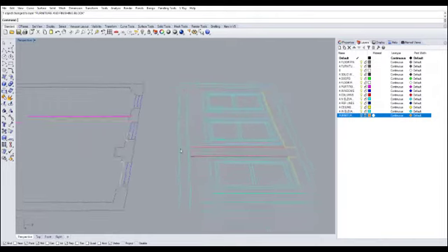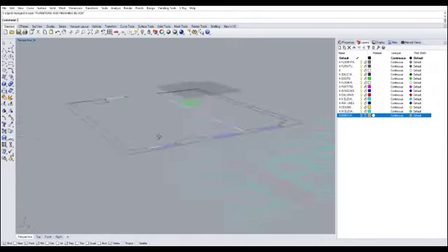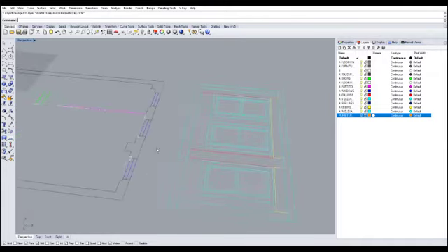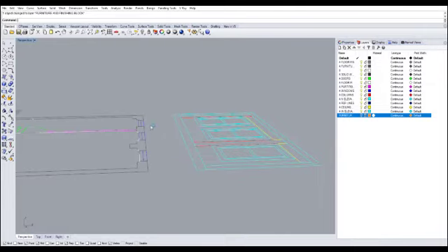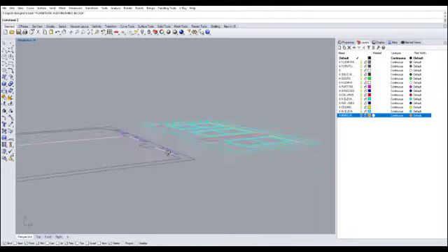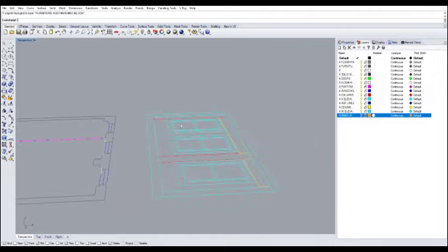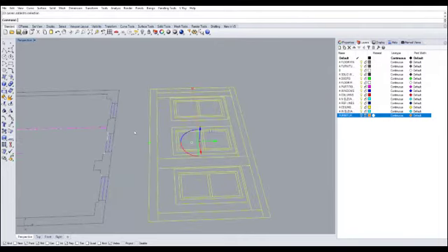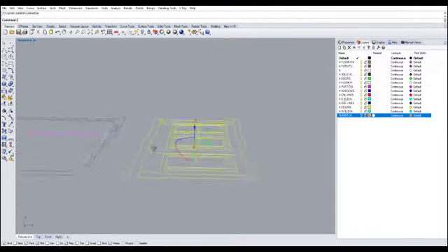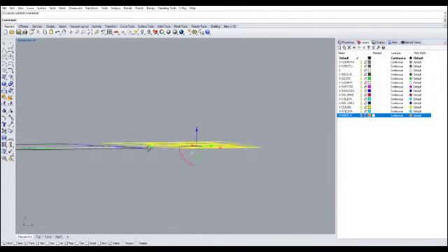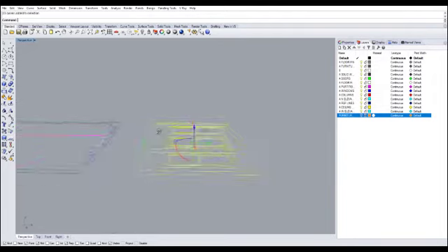And height information is necessary for us in terms of making a 2D plan into 3D, because it will tell us how to extrude or make it into 3D solids, or how tall or how high to make the 3D model. So for us to do that, let's also make sure that our elevation is in the right orientation, so it's a much more convenient, visible view, so that we can use that height information. And for us to do that, it should also be flipped upwards and upright, so that we can see the height information at a proper angle.